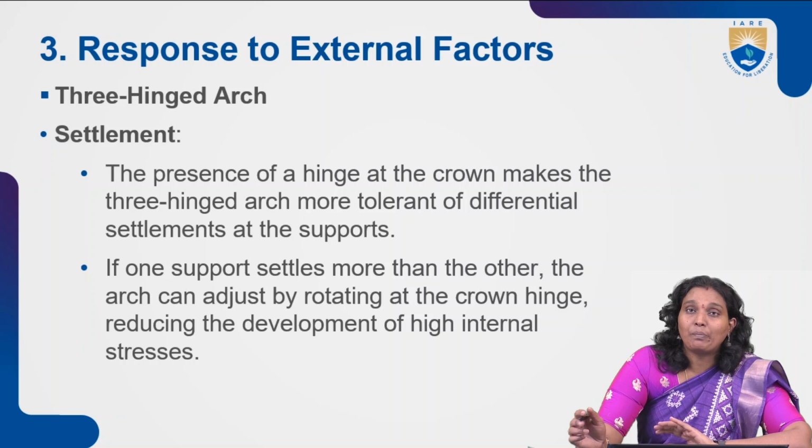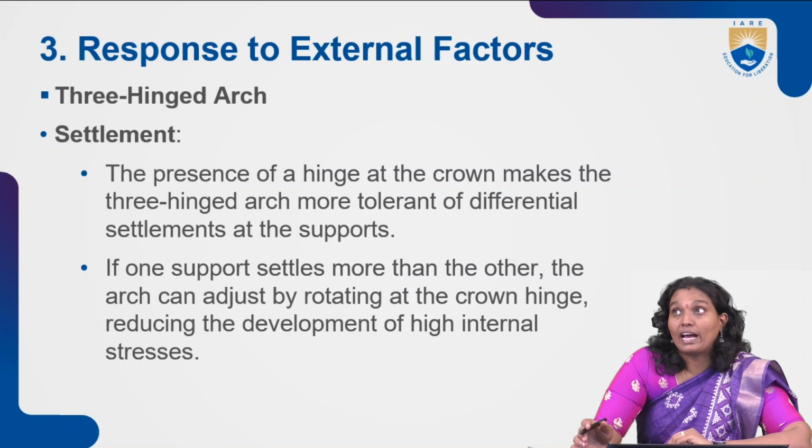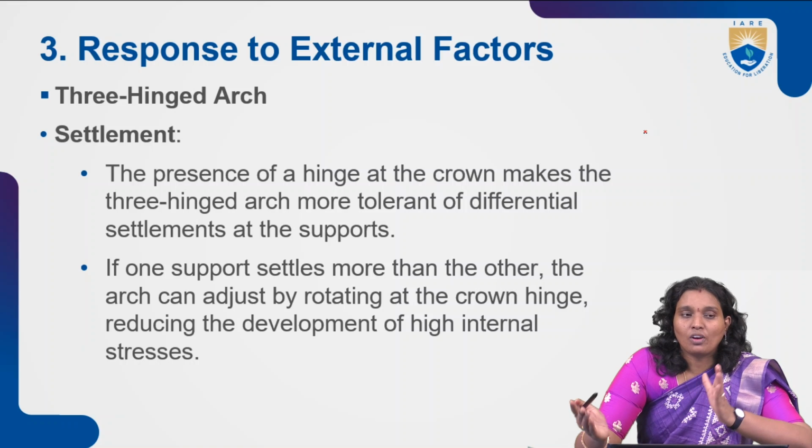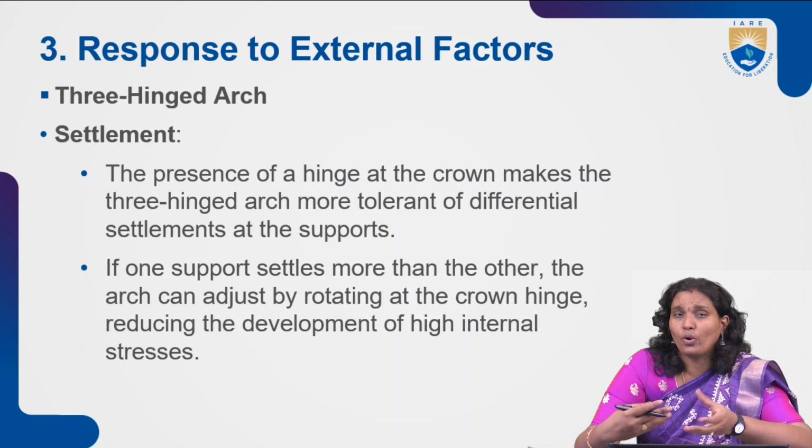The presence of the hinged crown makes three-hinged arches more tolerant of differential settlements at the support. Because of thermal stresses, that is thermal contractions and expansions due to temperature effects, the flexibility of the three-hinged arch allows it to rotate.